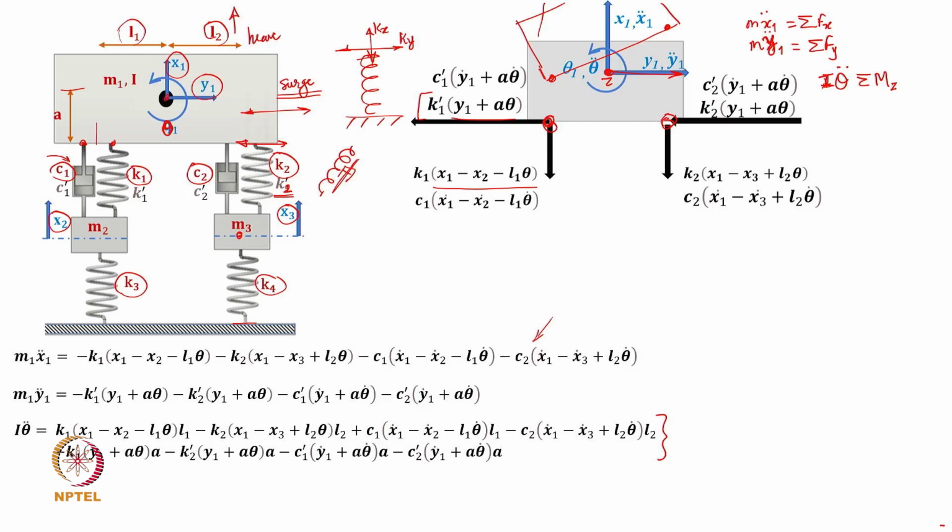That resistance to lateral motion is going to be quantified through Ky, or the stiffness in the horizontal direction, which in this particular case has been defined as K1 dash and K2 dash. So, the suspension could be like this at a certain angle, and then the damping will also be in parallel to it. All of that will generate both horizontal and vertical components.